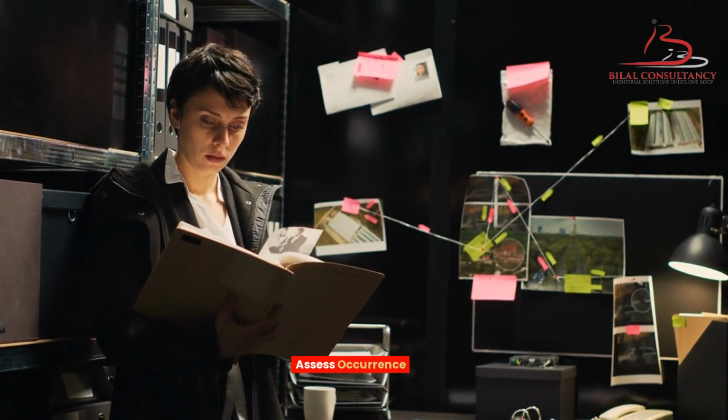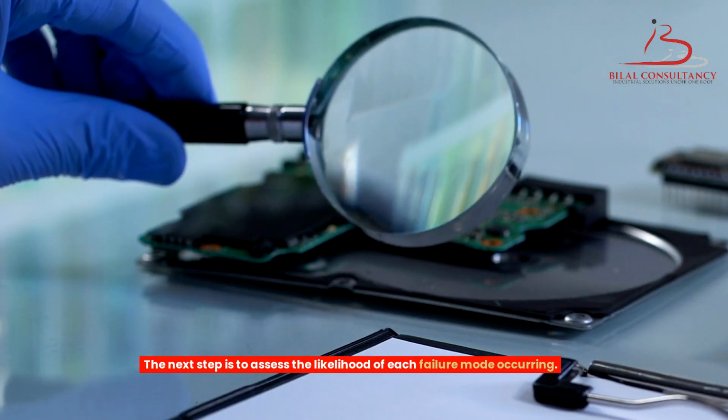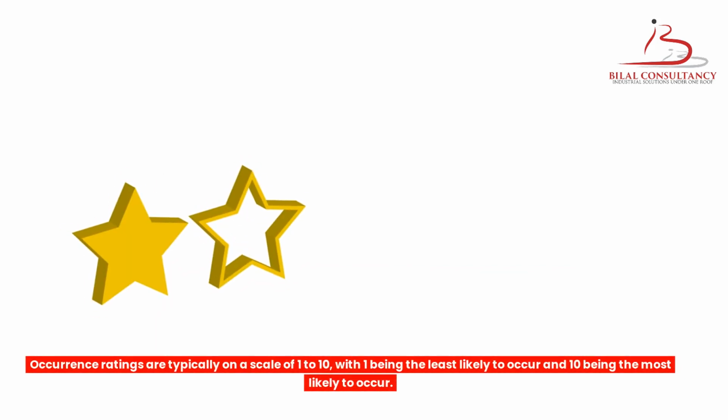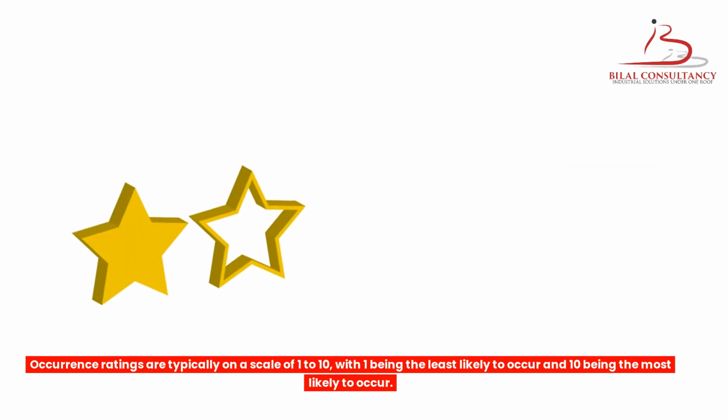Assess occurrence. The next step is to assess the likelihood of each failure mode occurring. The occurrence rating is a measure of how often the failure mode is likely to happen. Occurrence ratings are typically on a scale of 1 to 10, with 1 being the least likely to occur and 10 being the most likely to occur.